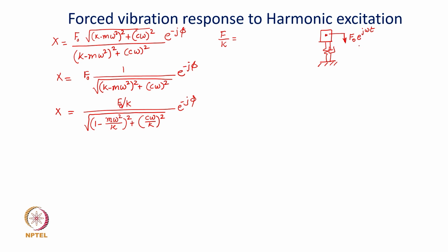So, suppose there is no frequency, I mean this force is static in the sense that it is not fluctuating with any frequency, it is a static load. So, what will be F naught by k? It means that if I apply, just like gravity, a constant force, this mass will deflect by delta, right, static deflection. That delta is going to be force divided by the stiffness offered by the spring. So, that is called zero frequency deflection. Sometimes in literature they call it static deflection.